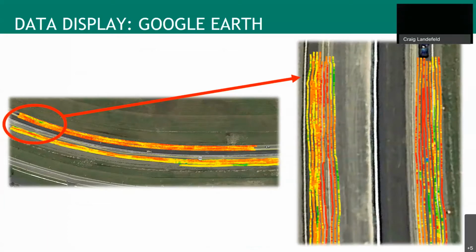There was actually some dirt on the pavement, and that's what the red circle up here is showing. We could actually see the drastic change in density or dielectric measurement as we went over some of that dirty pavement. We were just interested in that to see what it would do and how the equipment would react when we went over some less than ideal conditions.